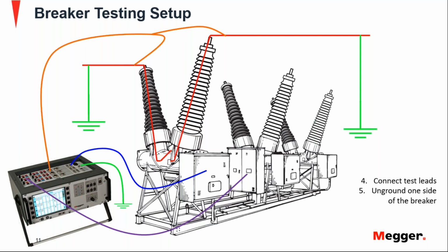So if the breaker operates and closes, these leads, these orange leads here, they are applying a small voltage, and depending on the manufacturer of the test instrument, you will have different ways to handle that signal, but in essence it is a signal that applies a small voltage, and as soon as continuity is detected, that's when the instrument detects the operating time of the contact. And I think I went ahead of myself in the slides, but I have another slide showing that.